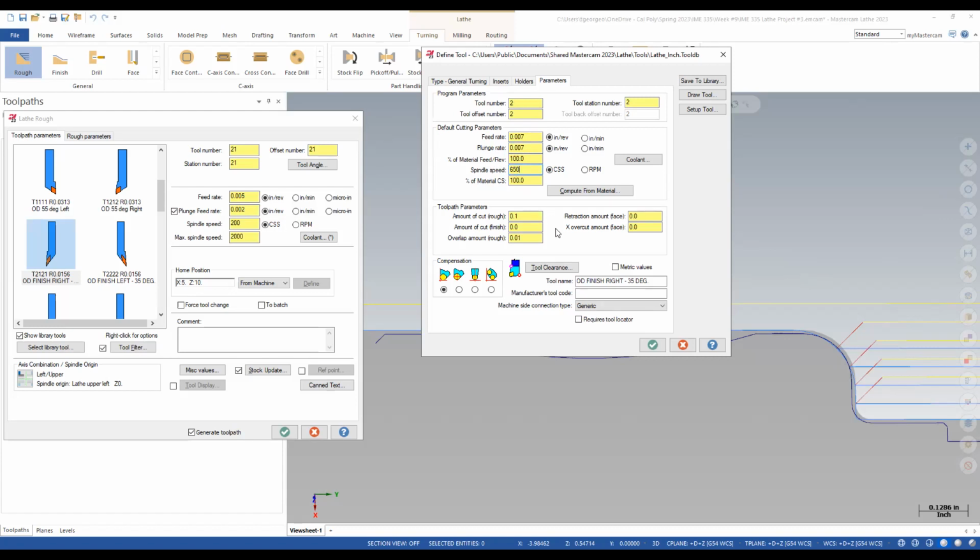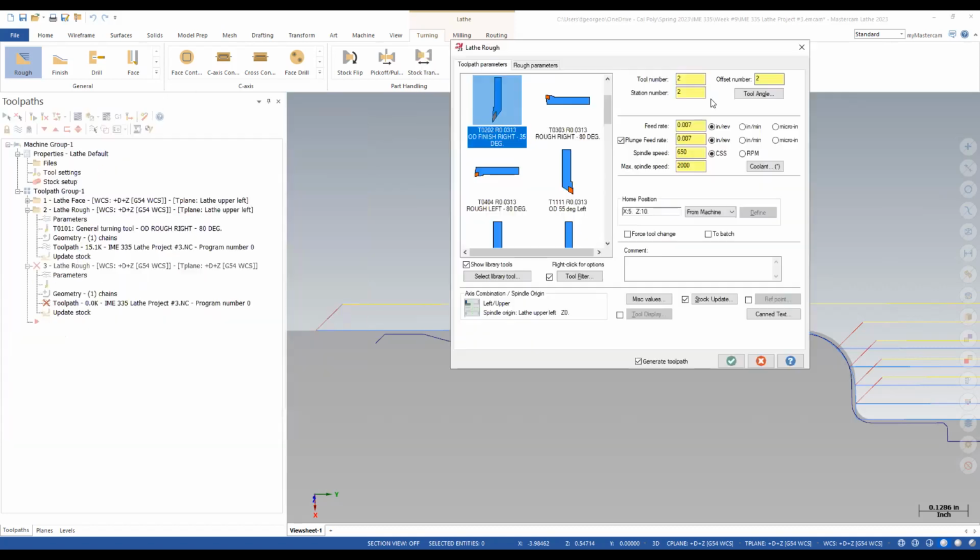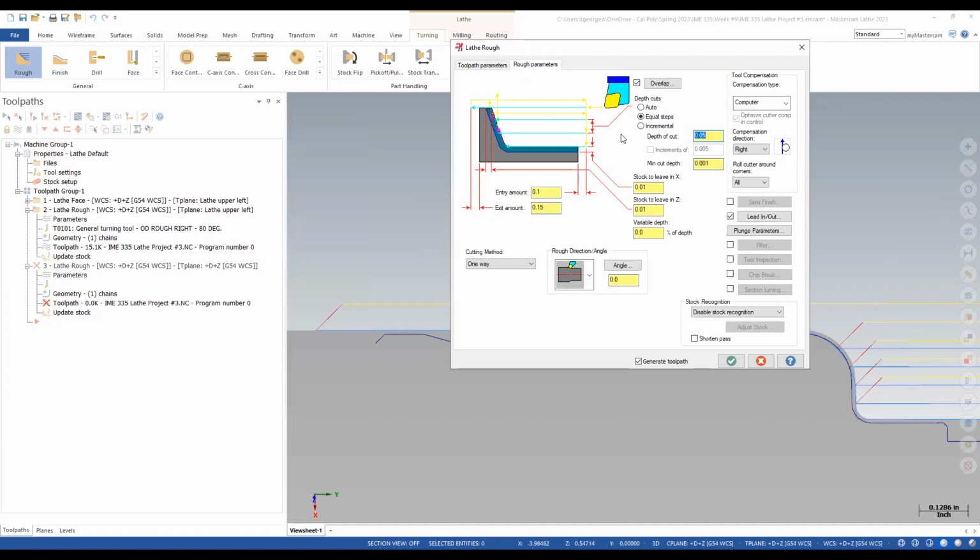And they don't have a spindle speed clamp value in here, do they? You'd think they would if it shows up in the other menu. So I'm going to go ahead and press check mark. Moving over here, 7,650, 2,000 maximum spindle. My rough parameters now, this tool is very sharp. It doesn't take a big depth of cut. We're going to run a 25 thou depth of cut with it. I think the slides say 35. It'll do 35 too. Do 25.